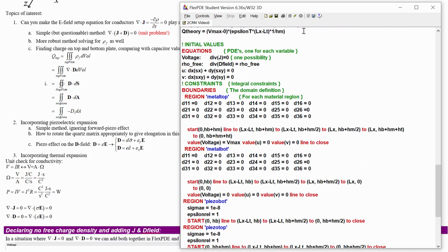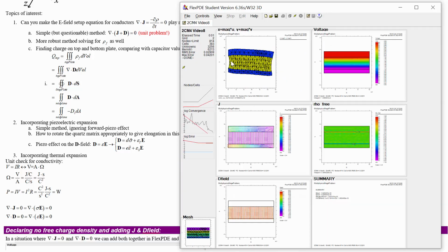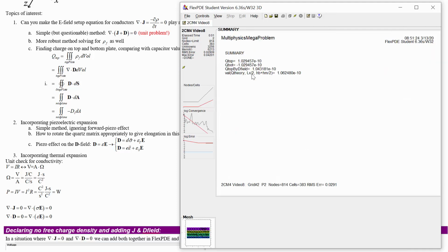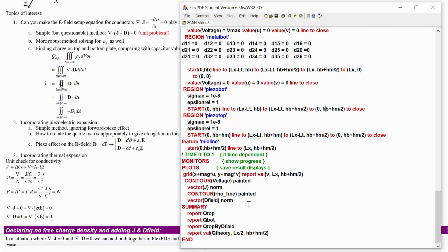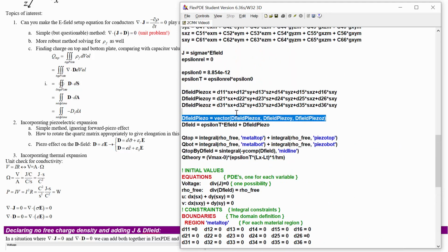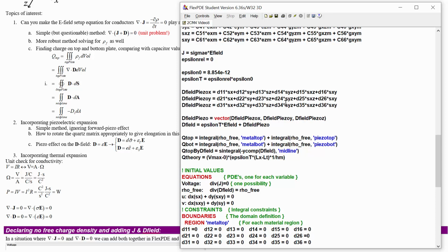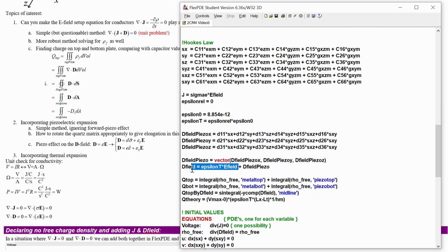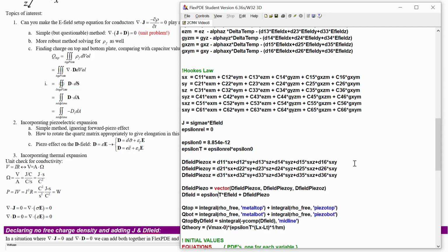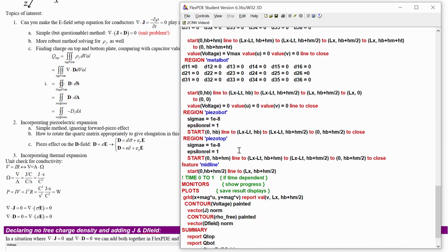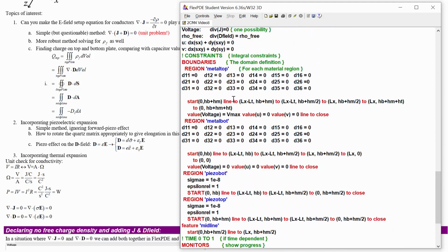In this setup, the stress is quite low because of the boundary conditions. So we don't actually have a very high amount of difference to the charge that we were getting earlier. For this to be coupling back, we need the D field to be modified by the piezoelectric effect. And if there's no stress in the material, then this isn't modified from what we were saying before, epsilon T times E field. So we could try setting up different mechanical boundary conditions.